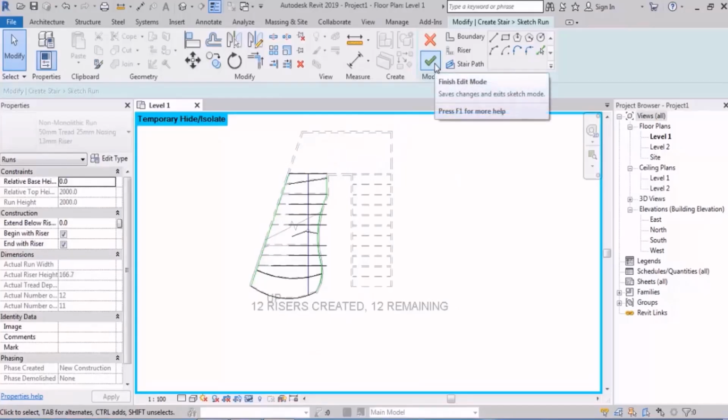Remember something, let me tell you before clicking on finish. Now, remember, after solving all the errors and all the mistakes, does the geometry that you have designed fit the landing? After all that, you might face that unjoined, that dangerous message now. Well, it might be like that. Technically, your boundaries, your risers, everything is okay, but the form you have created does not fit the landing. And I told you the trick, and it's up to you actually to change the form or do the trick.